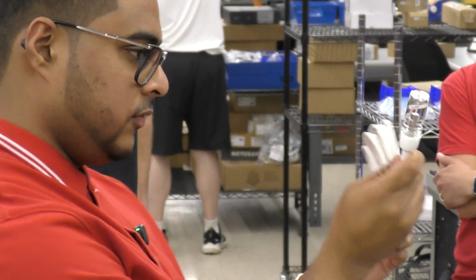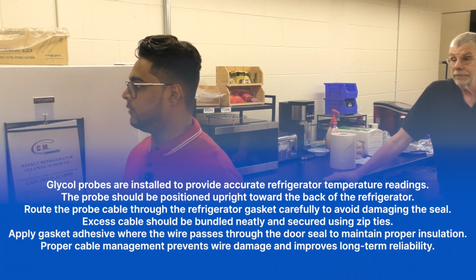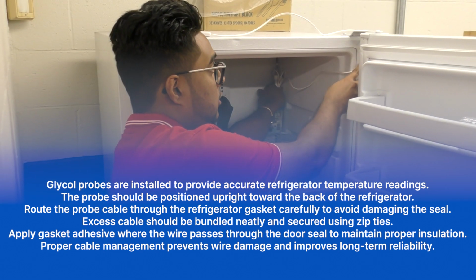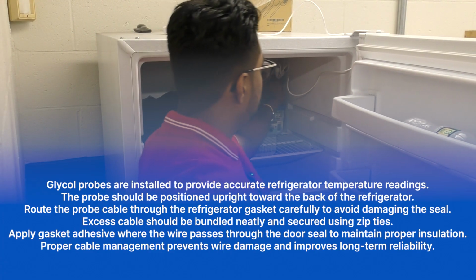Section 11. Glycol probe routing and placement. Glycol probes are installed to provide accurate refrigerator temperature readings. The probe should be positioned upright toward the back of the refrigerator. Route the probe cable through the refrigerator gasket carefully to avoid damaging the seal.